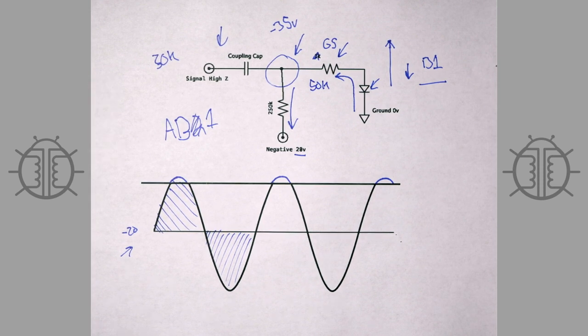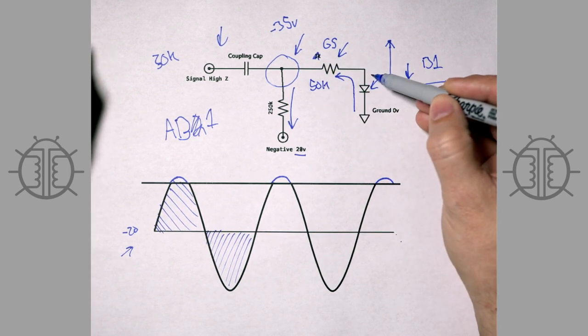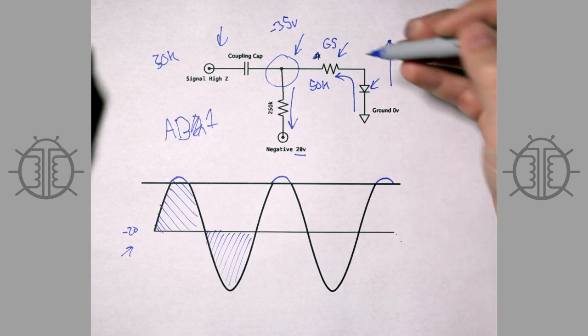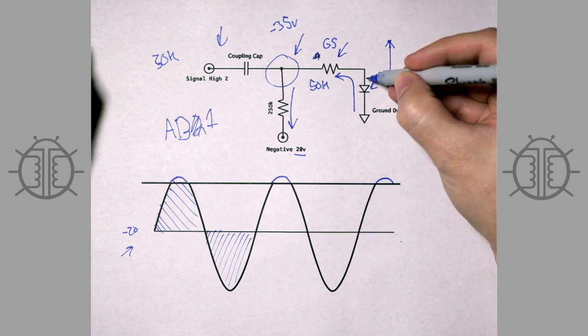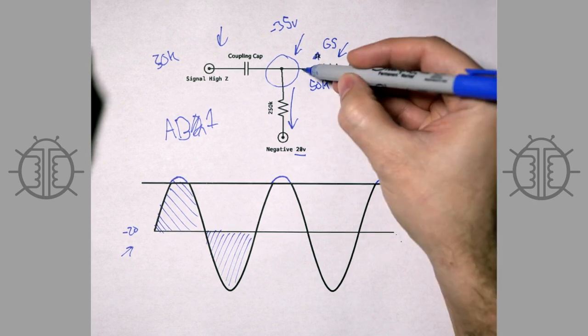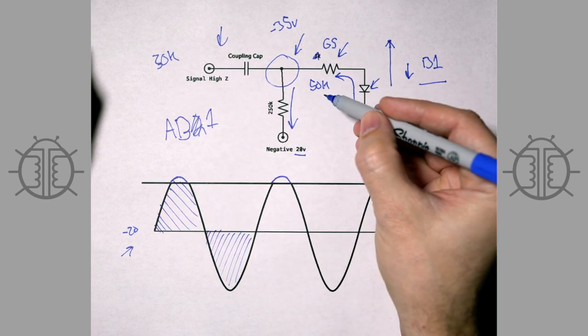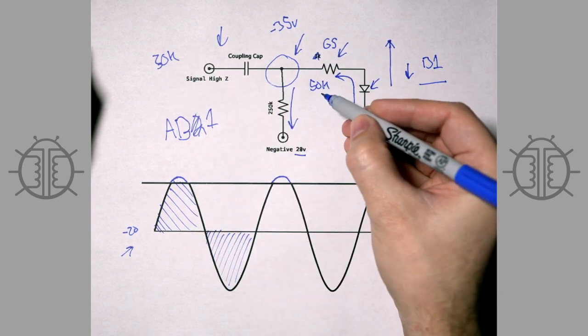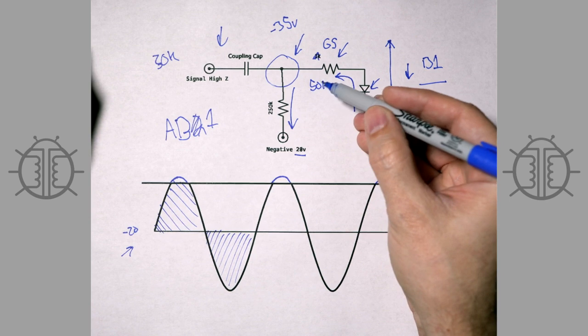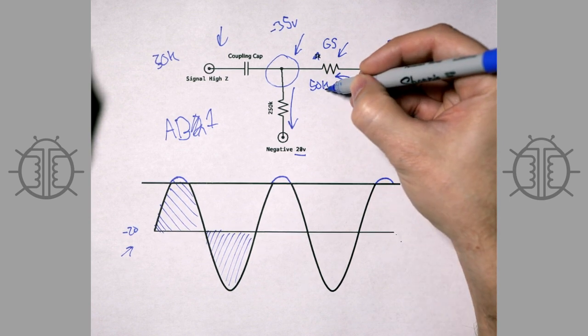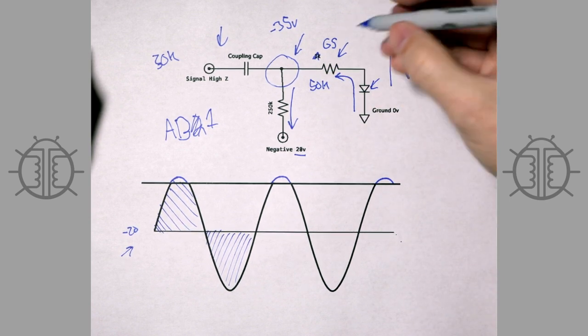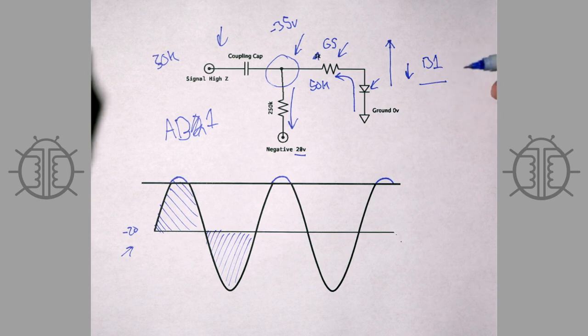It comes with some problems, but it's good because now when this diode turns on, the waveform over here is still going to be clipped right here. But over here, this 30K plate impedance may be perfectly happy for a brief period of time driving this 50K load right here. But still, you're running into the same problem.